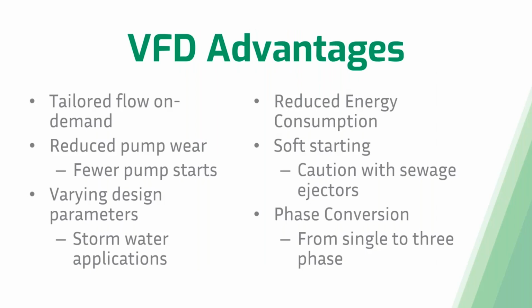So there are a lot of advantages to using VFDs. One is tailored flow on demand. So you can alter however much flow you're getting out of said pump to fit the current conditions of your application. Another thing is reduced pump wear. Typically when you're lowering the frequency, that pump is going to start fewer times since it's not putting out as much flow.